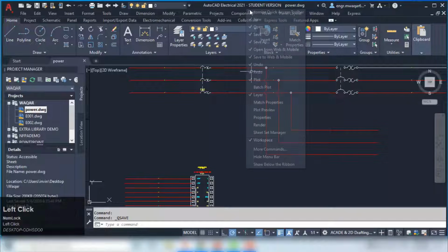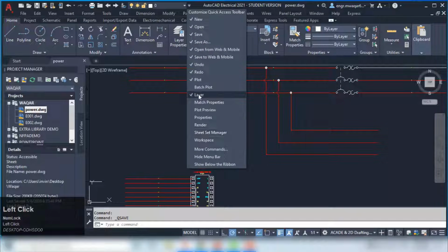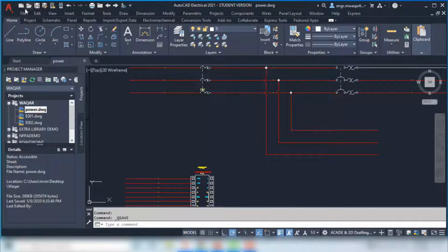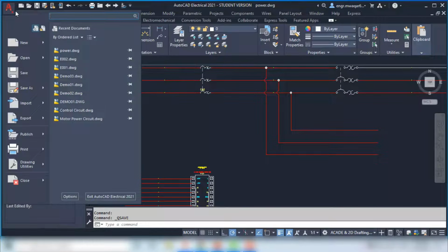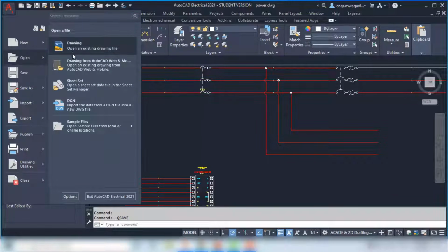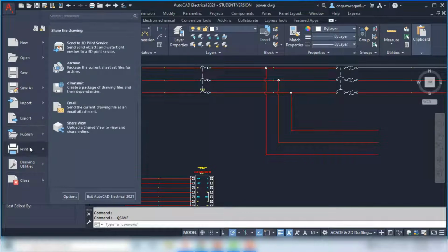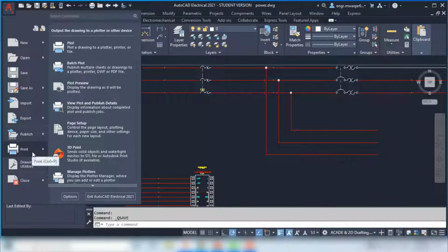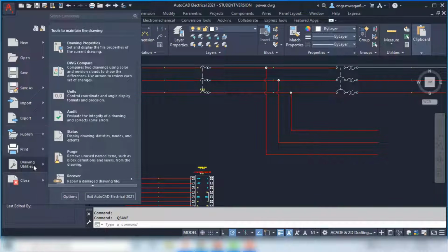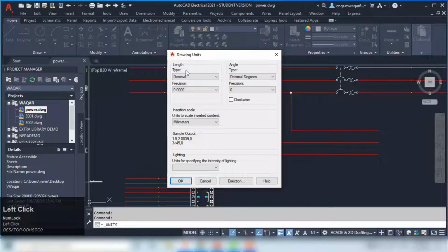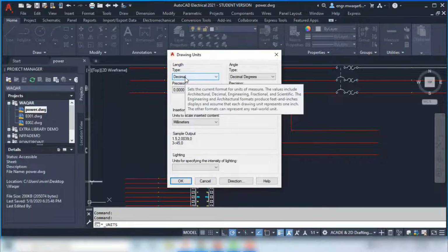I love that. And for anyone listening, that QAT is one of the easiest ways to customize your workspace right now. Absolutely. You should just load it up with whatever you use most. Layer controls, printing tools, whatever. It just cuts down your reliance on the main ribbon so much. And speaking of specialized tools, if you look at the menu bar, you'll see the familiar menus like File and Utilities, but then you hit the AKD specific ones, projects, components, wires, and panels. That's the specialized heart of the software. That's where you find the tools that understand electrical logic, like wire numbering and component tagging.